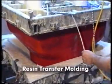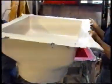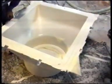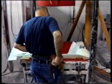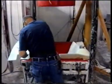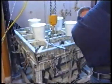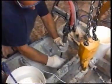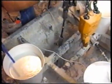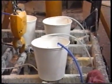Resin transfer molding, or RTM, is an efficient method of producing large and complex composite parts at faster rates than by other composite manufacturing methods. In one such method, a matched mold is loaded with the proper amount of reinforcement material, and the mold halves are clamped together. Resin is then pumped or gravity fed into the mold, infusing the enclosed reinforcement material. Air within the mold is vented as it is displaced by the resin.